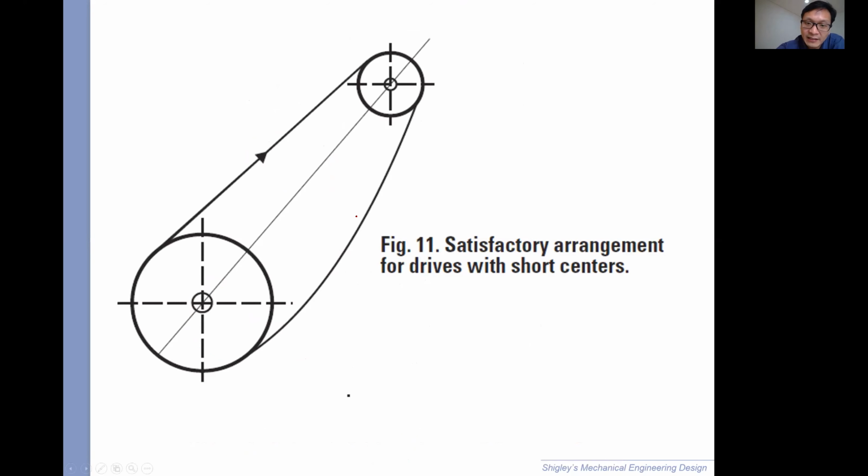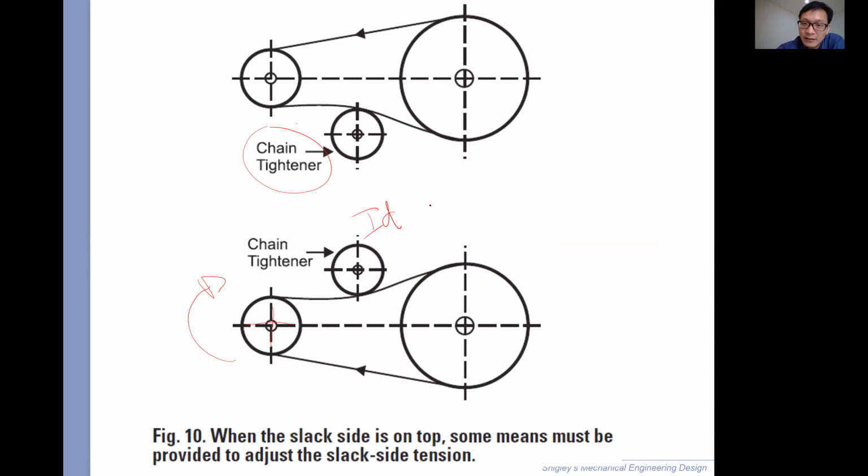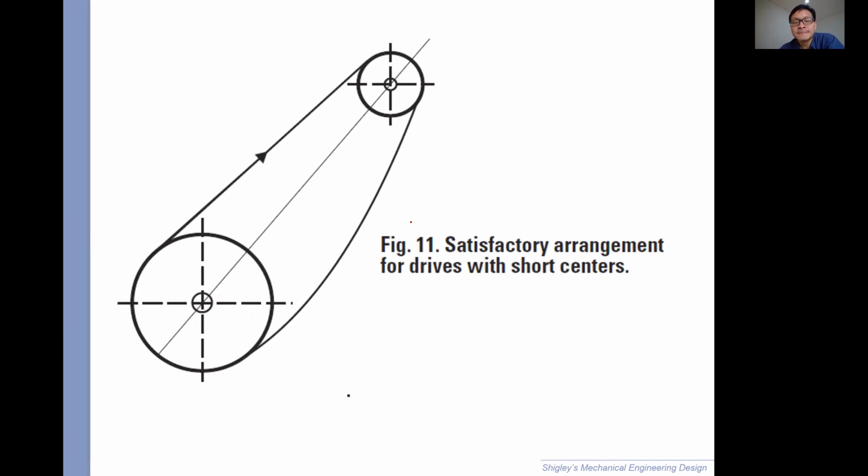Sometimes they call this an idler sprocket. Because it's idle, it's not carrying any torque. It's just there to push it down and it rolls on itself. Just like a belt tightener. A kind of tensioner, Pak? Yes, tensioner, right. This is good. Okay.